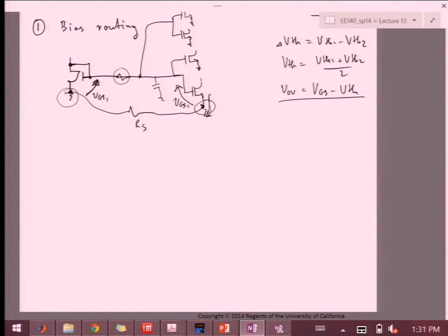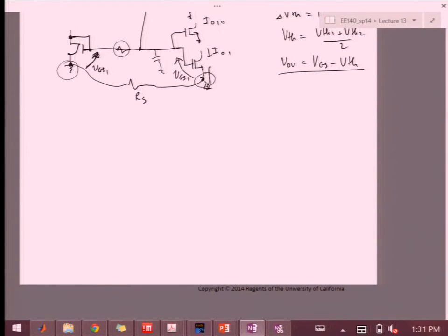You don't know what the resistances are going to be. It may be 2 ohms in one, 10 in the other, and all these small changes will cause all these output currents, IO1 to IO10, to be totally different by some amount. Okay, this is not random variation. This is a systematic issue, because once you build the grid, you know where things are going, but it's kind of hard to track.